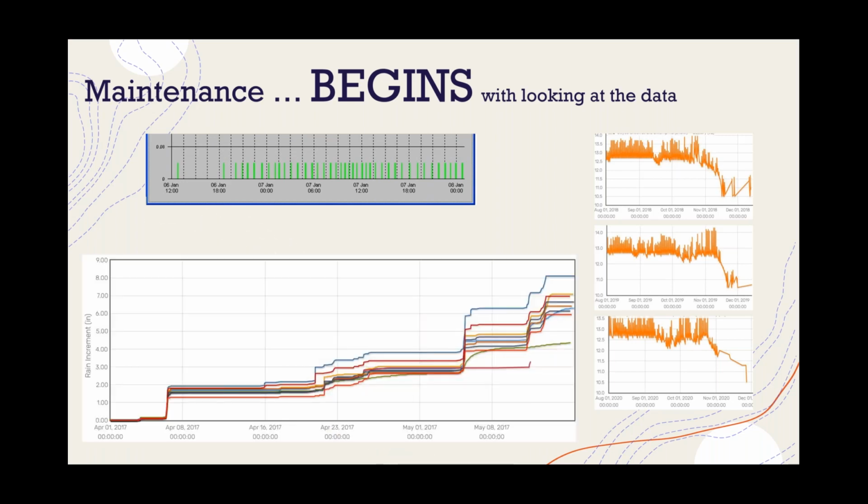And then looking similar as we did in that test bed, but looking at accumulated rainfall for a given area, a basin or whatever, look at disparities in the reported data from a collection of gauges, kind of what Jason was talking about earlier, when they compare gauges from different networks and use it as a means of quality control of their data. Well, you can do this before you go out in the field on your maintenance visits to see what is happening or has been happening in your network.